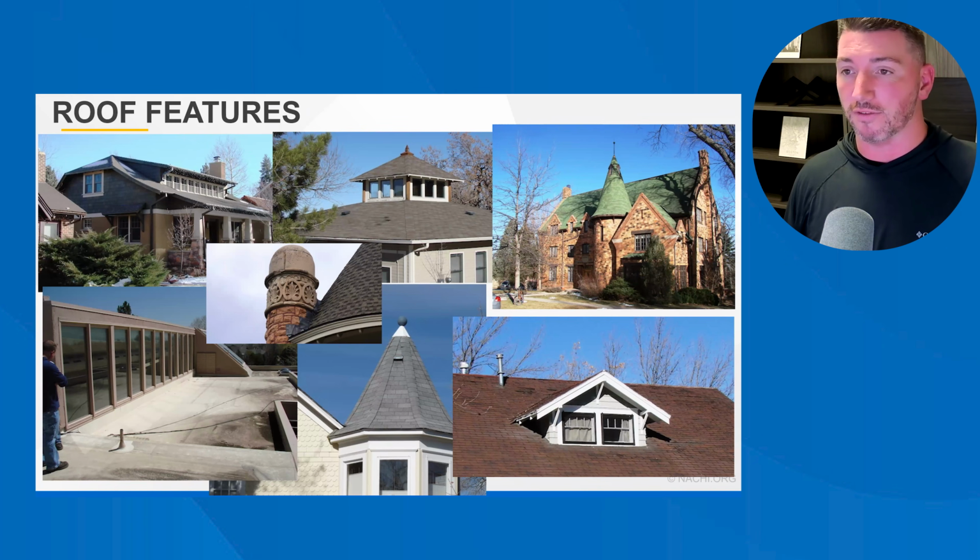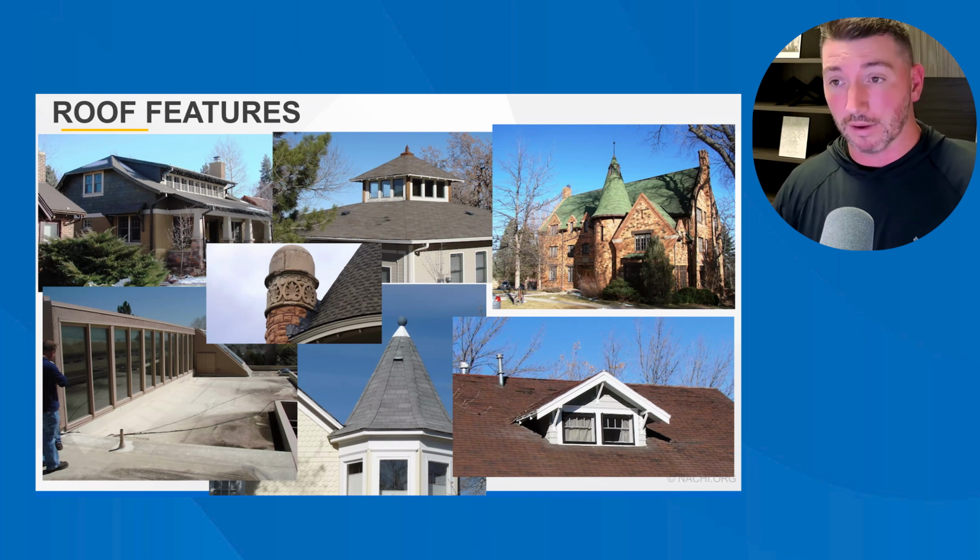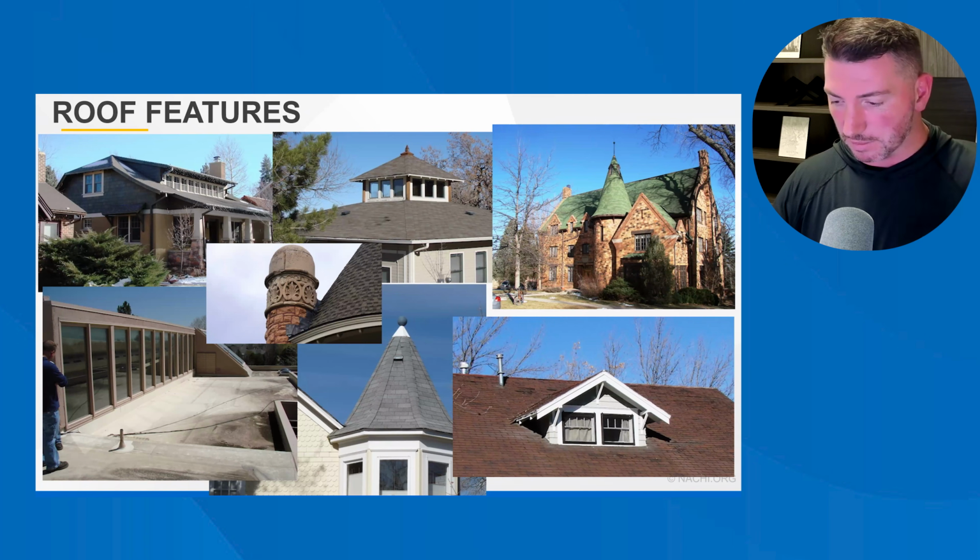And if you don't know what you're looking for, putting a bunch of roof photos is not good when you say the roof's okay when it's not okay, or calling out issues that are there that are actually not issues at all. So a contractor may need to hook a ladder over the ridge in order to get high enough on the roof to see the backside of that conical roof clearly. That's especially true when the roof is covered with fragile materials such as slate or tile.